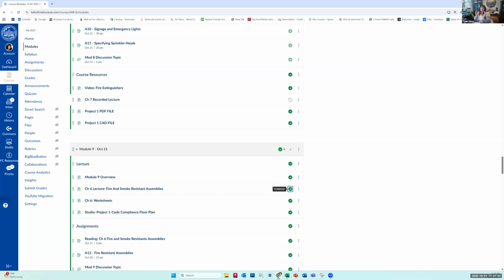I know at one point you had mentioned recessing the doors, so I was trying to follow the measurements given in the book. I also did one with the 180-degree opening into the corridor, because it said as long as it wasn't deeper than the 7 inches, you could have a door that opens that way as well. I put both in there because I didn't know exactly what you wanted.